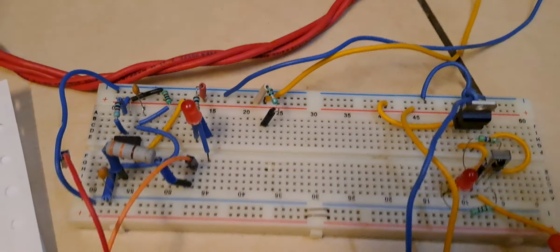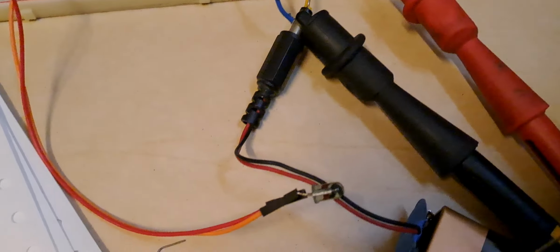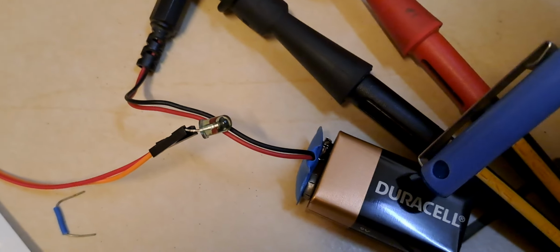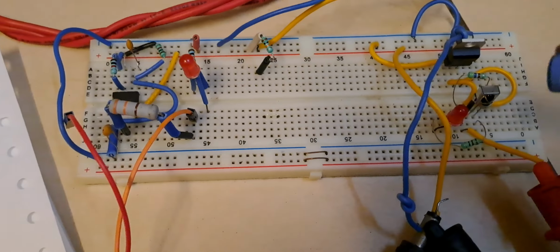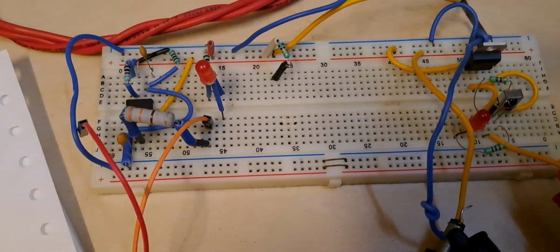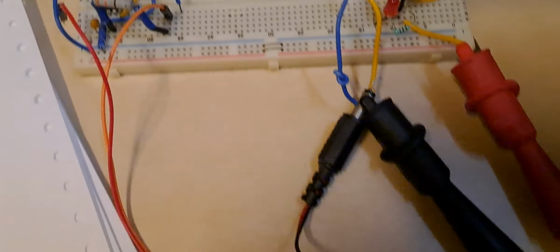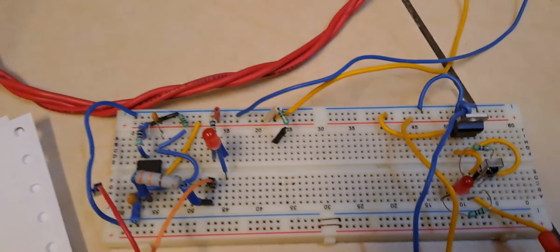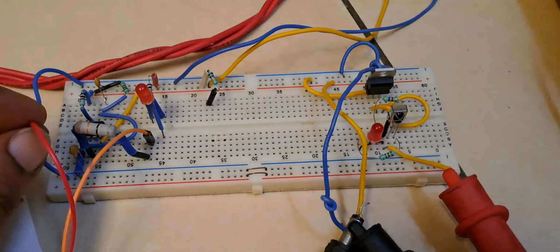Here you can see this part is the receiver part. The receiver is powered with a battery. What I have noticed today is that if we use the same power supply for the transmitter and receiver, there is interference happening. That's why I have used a battery powered DC supply for the receiver. So this is the receiver circuit and this is the transmitter circuit. Now I am going to trigger the transmitter and we will see the receiver.